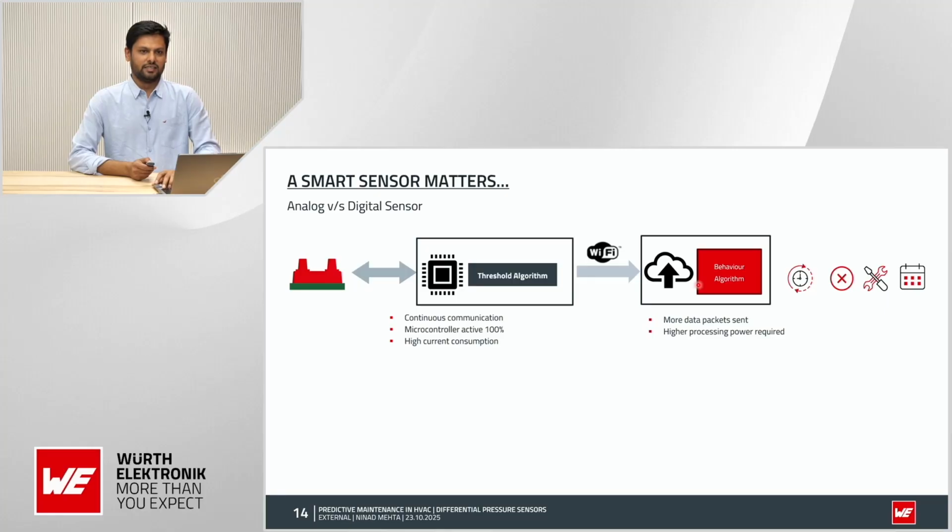What happens here is that it requires constant communication between the microcontroller and the sensor. So your microcontroller is always active, and this also adds more current consumption, and you are also sending higher data rates and more packages of data. So you also need higher processing power.